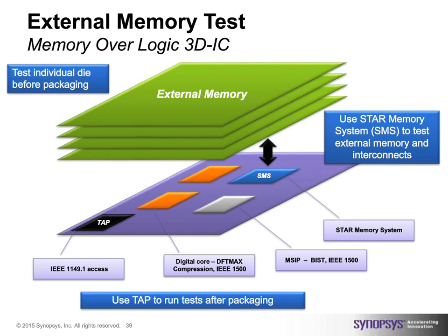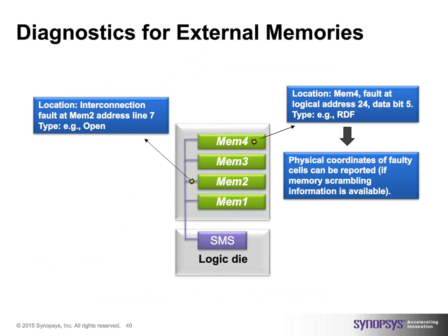What they do is they allow you to provide the test and the diagnosis necessary for that purpose, and the handshake will allow us to do the necessary high-speed connection, and with that high-speed connection, find out where the problems are, and of course, replace them accordingly. So finding out where the problems are means diagnosis. If you have multiple memories, find out which memory is failing. If you have multiple interconnects, find out which interconnect is bad. Because replacing that whole unit is very expensive. Maintaining the expensive SoC and changing the interconnects or the memories is much cheaper.